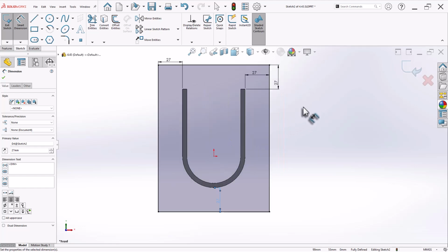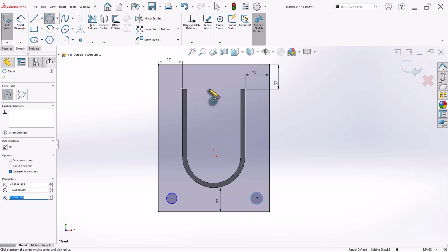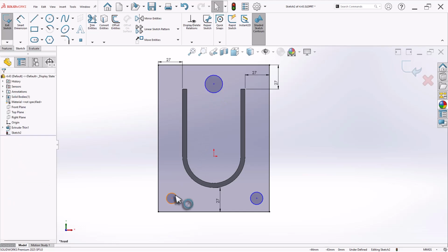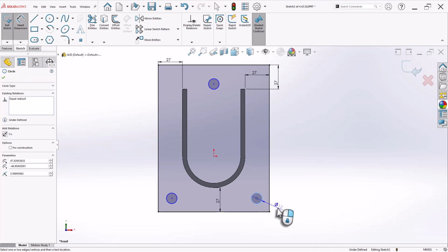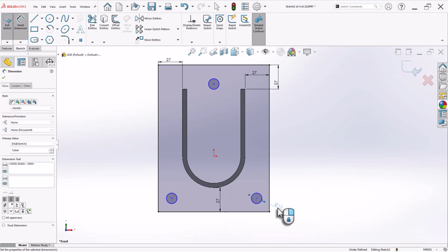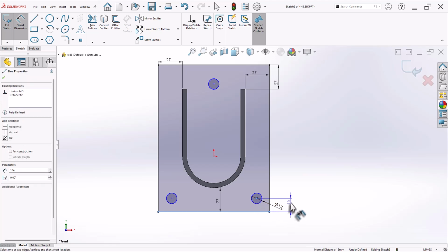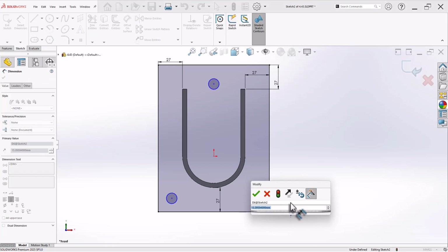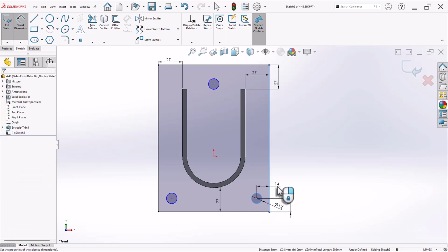Now along with that rectangle, let's draw circles. So in one sketch, we are able to create the geometry. All these 3 circles are of equal diameter. So let's make them equal. Now they are located from the bottom edge at 15. From the right, it is again 15.